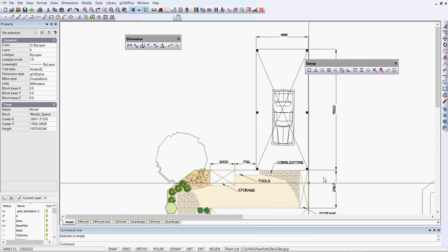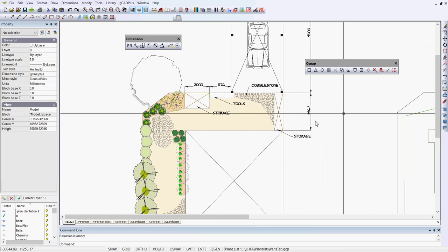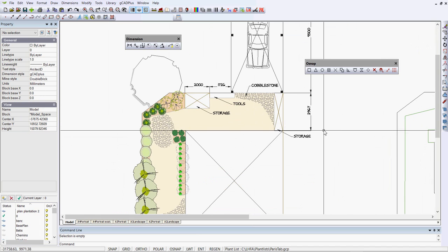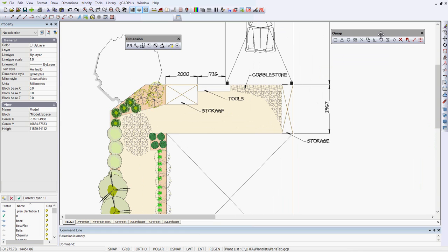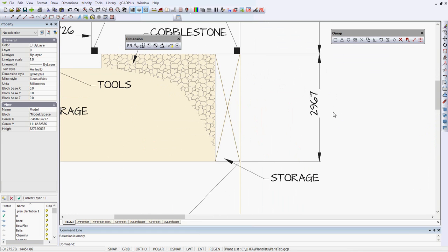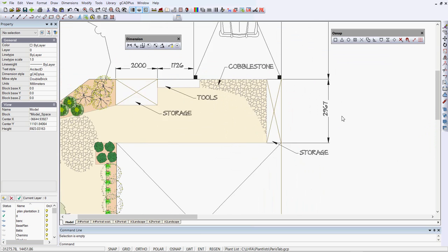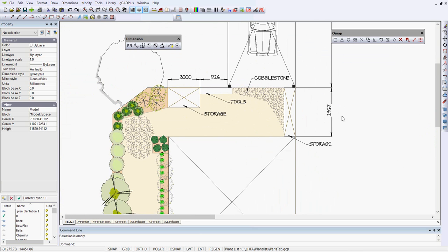I would much prefer you draw accurately first rather than overtype these values. We've seen rather expensive problems occur when people overtype dimensions. So do watch out for that. It's better to draw accurately. So putting dimensions on in your drawing really provides you with another check of your design, how accurately you've been drawing.